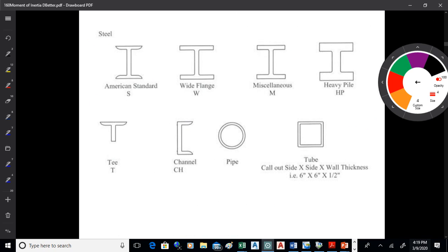So let's look at what's happening with an I-beam. Maybe that wide flange beam is the place to look. See, here's the neutral axis through the centroid. What they're doing, they're putting those big flanges out away from the neutral axis. They're using their area as efficiently as they can, setting it out away from the neutral axis.